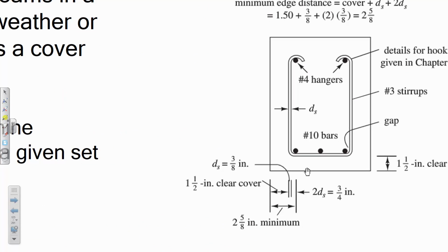You are right that that's going to affect that. From a design perspective, what we're really worried about when it comes to aggregate size is how far apart these bars can be. In this table right here, what this table does is it assumes a maximum nominal aggregate size of 3/4 of an inch, which is really common for internal beam and column type applications.